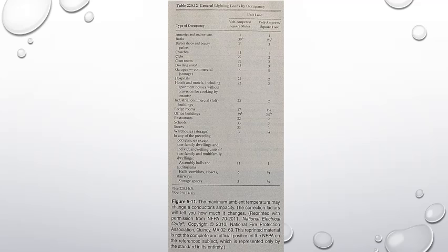Conductor identification. The NEC requires that all electrical conductors be suitably identified. This is accomplished by having proper markings and insulation coloring. These two methods ensure the correct wire type is used during the installation and that the conductor's purpose can be identified at any time.